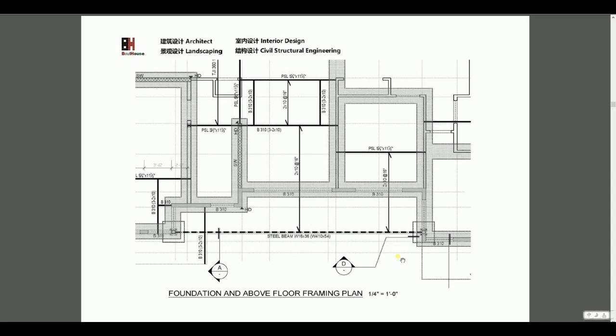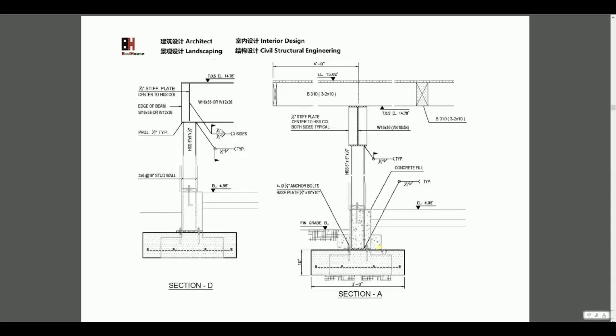There's another one. If the span is too big, for example a 30 feet span, the wood beam or PSL beam, parallel beam, doesn't work. Over 25 feet doesn't work. We need a steel beam. This is another project we did before. We have the steel beam here. We'll talk about the steel later.